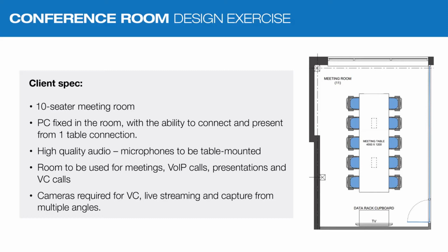Turning this into a Q-SYS design is quite straightforward. The bill of materials will not be that large. We'll use the Core 110F for this, for the audio DSP. Multiple cameras is straightforward without any extra infrastructure added. Just add the cameras, USB bridges if needed, to the switch, and we're good to go.